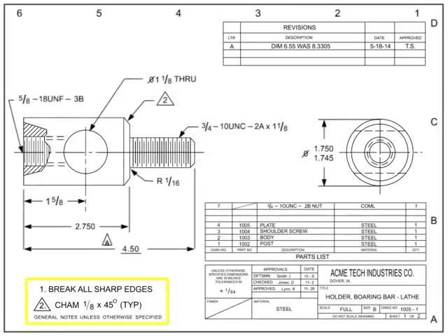The notes list conveys information that the callouts within the field of the drawing do not. It may include general notes, flag notes, or a mixture of both. Traditional locations for the notes list are anywhere along the edges of the field of the drawing, but most are typically found in the upper left or bottom left corners.